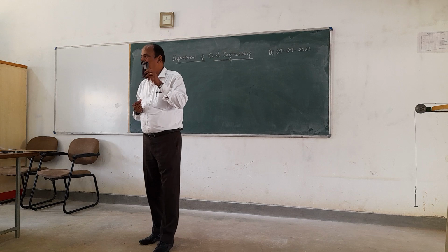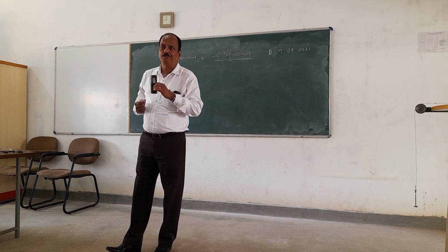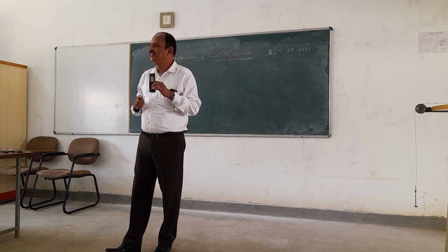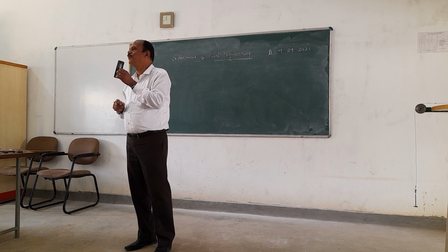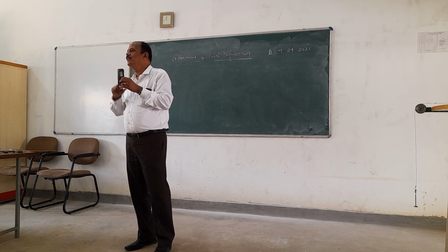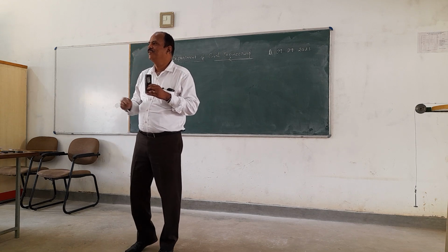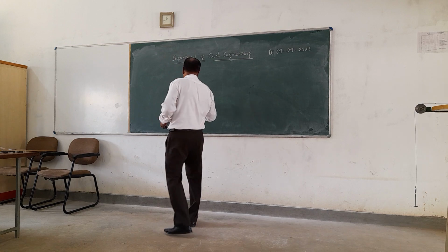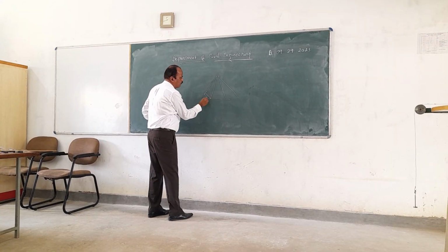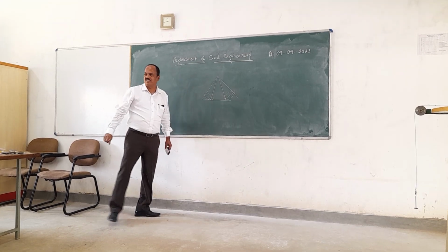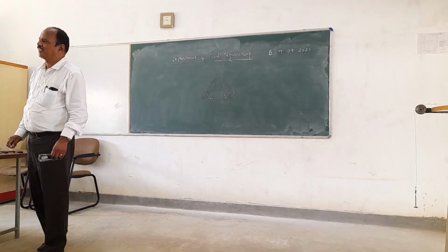A vertical slender member which is subjected to purely a compressive force, in general we call a column. And how are we going to differentiate it from the strut? A strut is also a compression member, but it may be inclined or vertical. That short compression member, in general, we call a strut. Where do you come across a strut? For example, in the case of trusses. In this particular truss, this member is a strut which takes up the compressive force. That, in general, we call a strut.